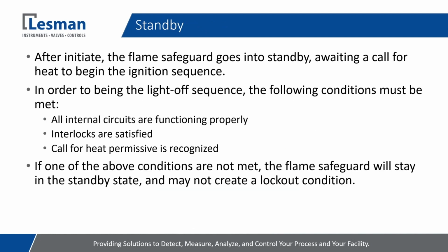So after initiate, we go into standby. Essentially, it's just saying, hey, my flame safeguard checks out, but I haven't received a call for heat yet. So I'm just waiting until you tell me that it's time to go. When it's in standby, it's waiting not only for the call for heat to come in, but you also have your interlock string.